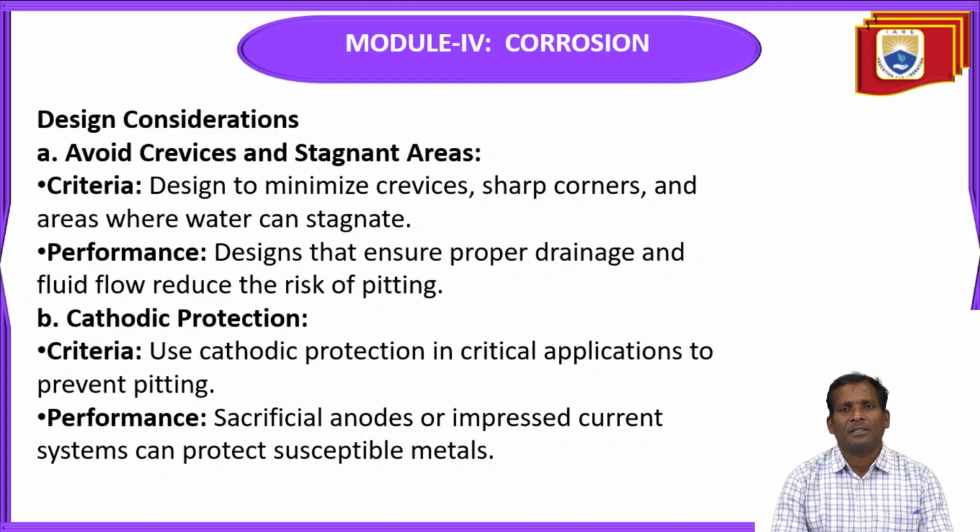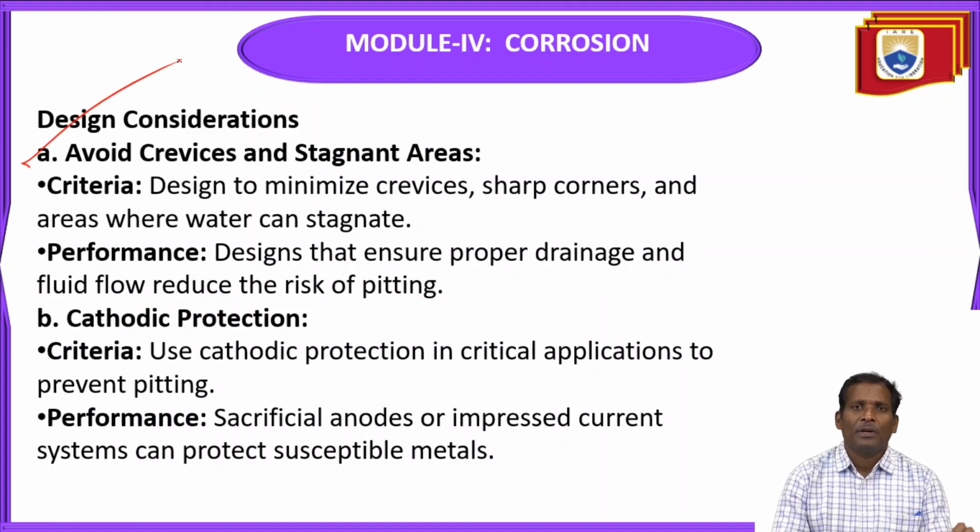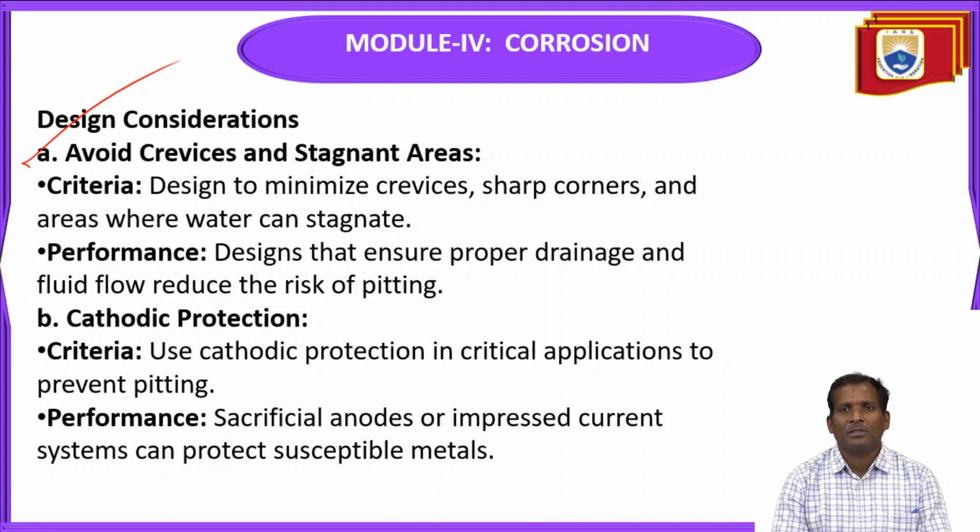So next, design considerations. While designing a component or product, design to minimize crevices: the joining parts, curved parts, undercut parts, sharp corners and areas where water can stagnate.